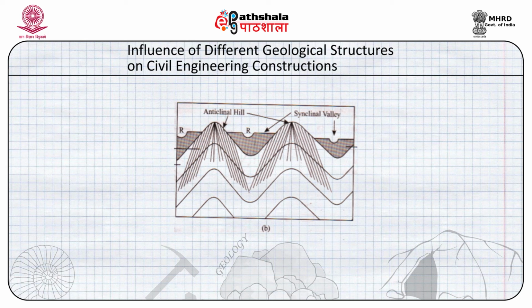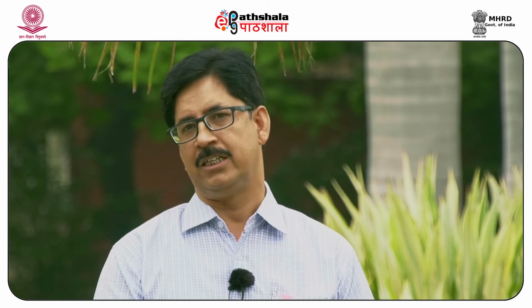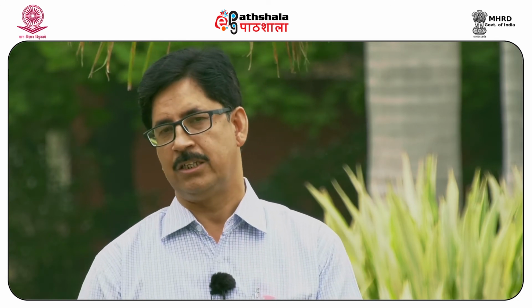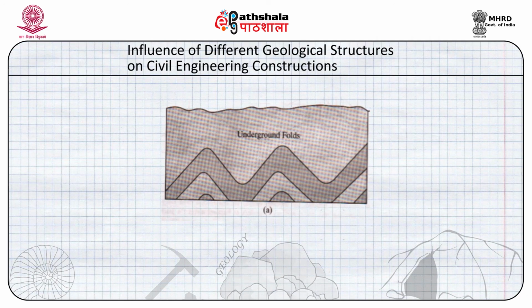So, anticlinal zones are usually weak as compared to synclinal zones, where you have compressive stresses and the number of fractures is less. So, if you are making any structure, you will come across many fracture systems in the anticlinal zone and fewer in the synclinal zone. For example, if you are making a tunnel, it will be difficult to make it along the synclinal zone because of compressive stresses. The rocks will have very high strength, so the rate of driving the tunnel will be very low.